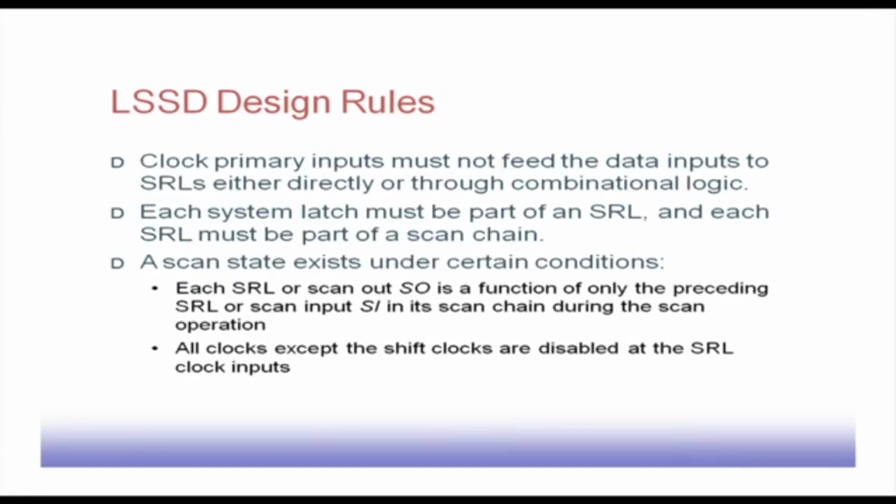Then, clock primary inputs must not feed the data inputs to SRLs either directly or through combinatorial logic. So, this clock primary input should not be connected to the data input, for the same reason that in that case the data input will also change when the clock input is changing. So, when the clock input is changing, if the data input changes, then of course there may be a setup hold timing problem.